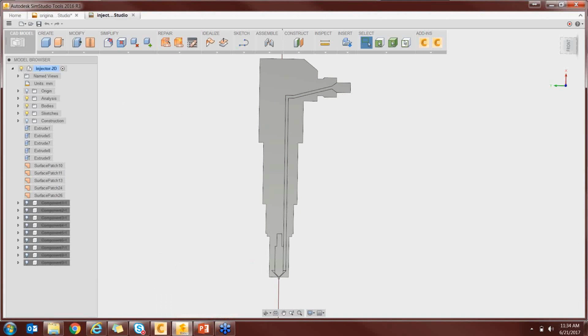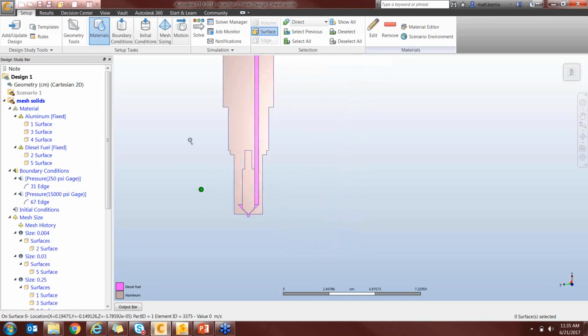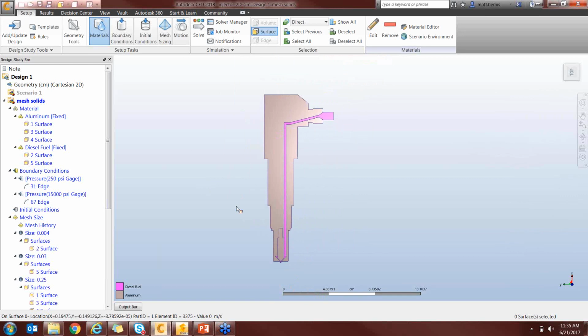The basic idea is, first of all, conceptually, before you start doing your model, say, okay, would I benefit from doing this as a 2D? Can I do it as a 2D and then create your 2D model by just taking a slice and prepping that model? If you can do 2D, you should definitely do it, especially if you have multiple iterations that you want to do, because the time savings are going to be huge. Like I said before, it might not be your end goal, but it gets you to your end goal much, much faster. Right. And it lets you work out the hard lessons fast, so you're not spending tons and tons of time.